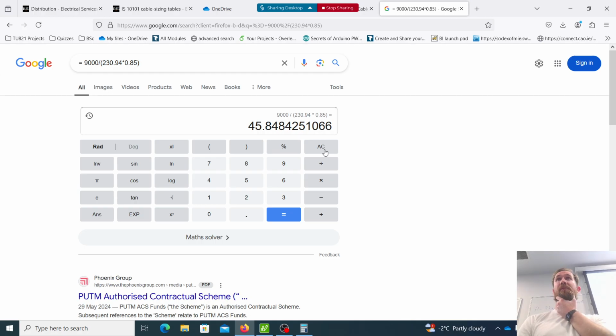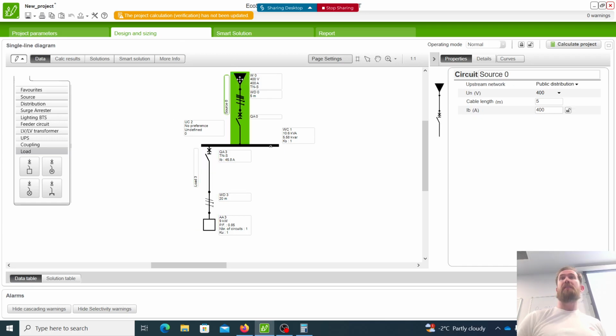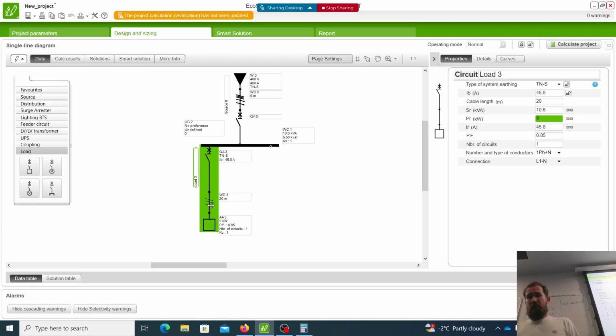All right. So we're saying it's 230 volt single phase, which, you know, it kind of is. The reality is in this system, the source is a 400 volt three phase, so that little 0.94 of a volt is making that much of a difference. Good spot. Make sure that's in your report. That's very well spotted. Fair play. Okay, so we now know we have the right current.